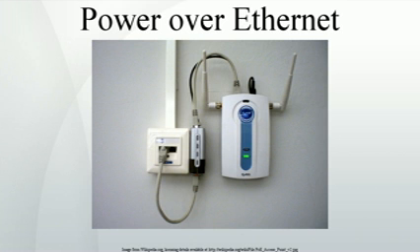Passive. Most passive applications use the pin-out of 802.3af Mode B, with DC plus on pins 4 and 5 and DC minus on 7 and 8, see chart below. Data is then on 1 to 2 and 3 to 6. This limits operation to 100 Mbps.